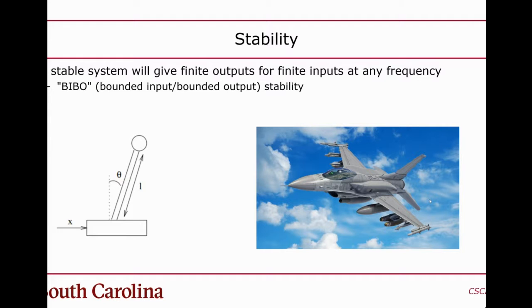In fact, you can even bump the yoke, and when you first bump it, the plane might go down or up, or it may bank to one side or the other, but it'll eventually just by itself stabilize out and go straight. Whereas the F-16 is actually inherently unstable. If you didn't have the benefit of a computer controlling it, and the pilot had direct control, then holding the stick straight wouldn't make the plane fly straight. It would go out of control immediately.